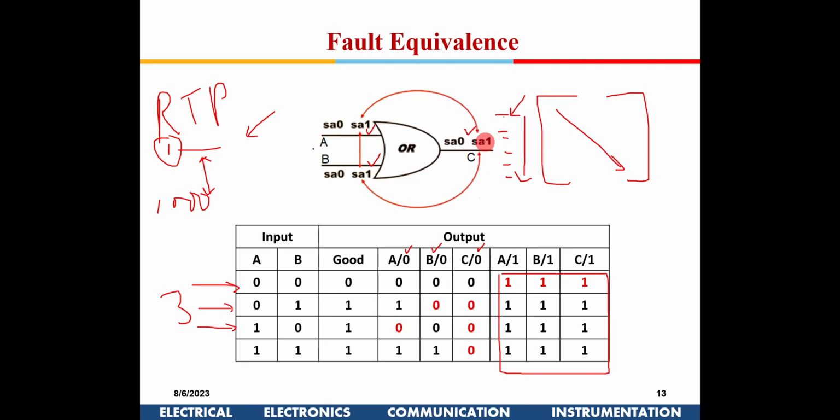Now, we will do fault collapsing and try to detect whether there is a fault with a gate or not. This is my first run. Subsequently, once I have identified that this gate is faulty, I want to give more information to the fab lab engineer, to say in particular whether the input is stuck or the output is stuck. I might want to run more detailed fault analysis.